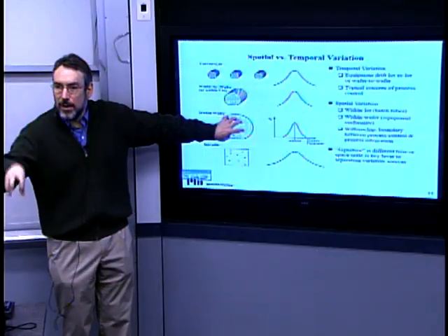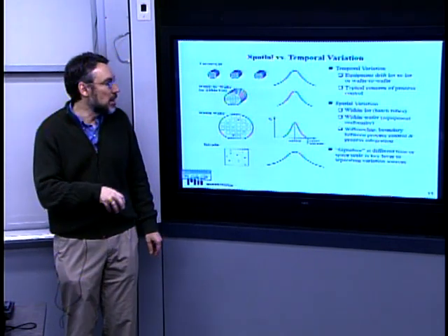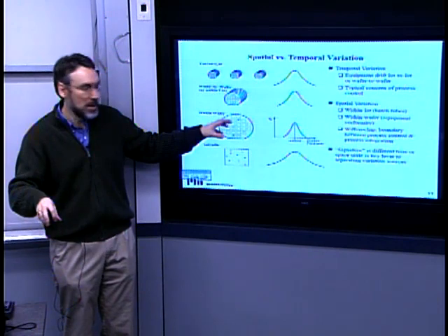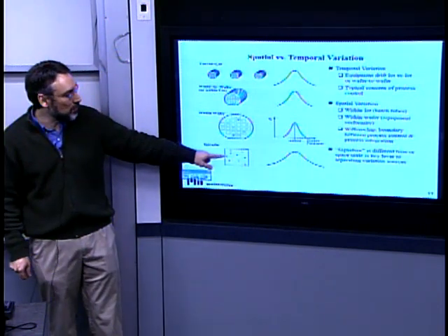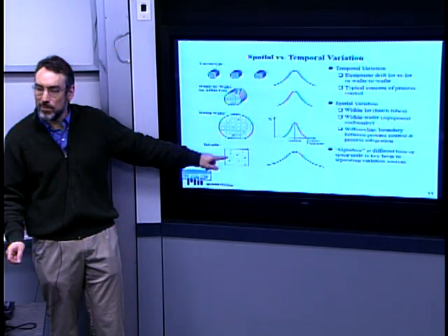It may be we're doing that photolithographic stepping, and every time I have a little bit different overlay control or offset control. So this distribution may be because of wafer level or across wafer sources of variation that are very different than the sources of physical variation of replication of transistors within the chip.